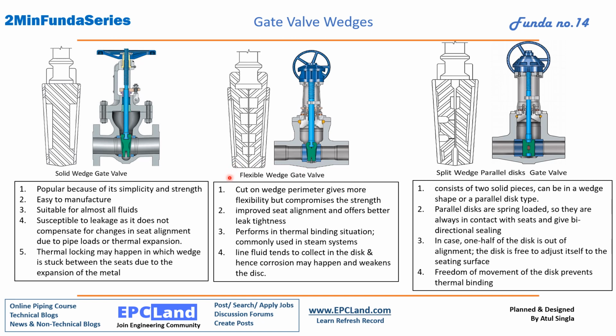Then another type is the flexible wedge gate valve. What is different here from solid wedge to flexible wedge? A cut on the wedge perimeter gives more flexibility but compromises the strength. Here what we have is a cut in between.